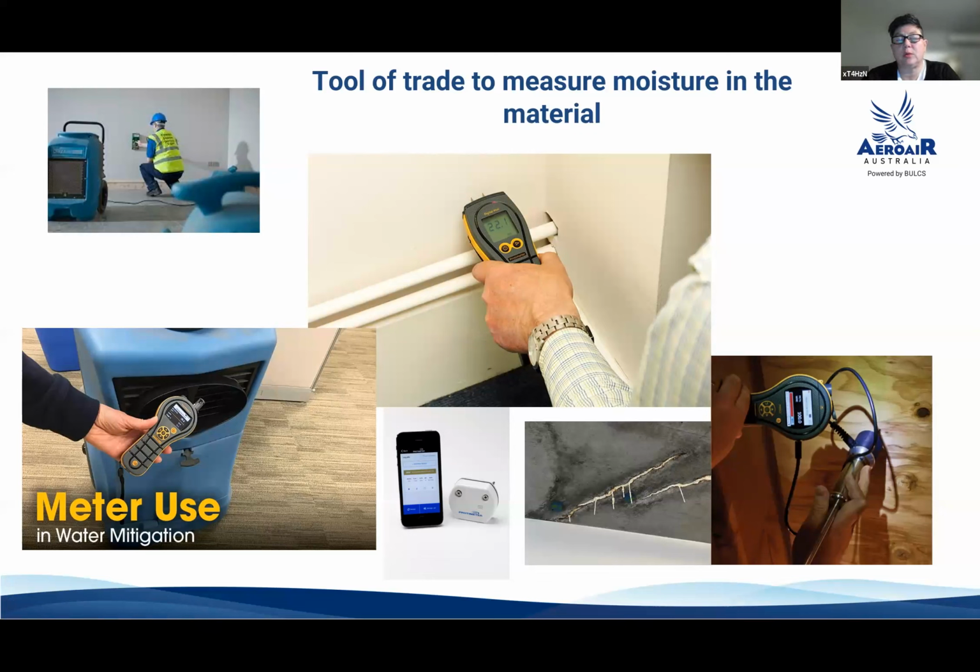It is just a measurement. It's a qualitative reading, not a quantitative reading. It's kind of like saying, yes, we think that this material is wet. However, that can be hindered as you move your meter across the building materials. At the corners of building materials, you will find there are always some metal straps, and that might give you a false reading.